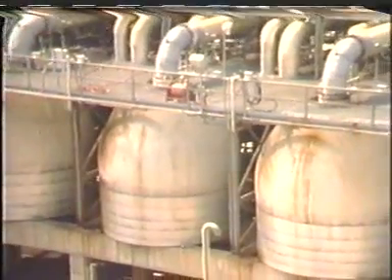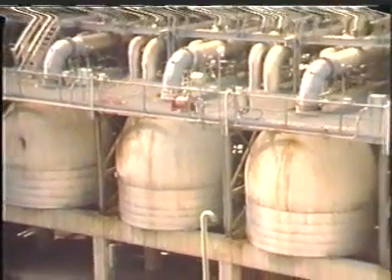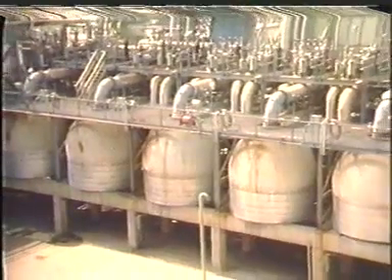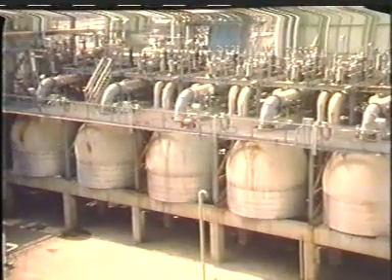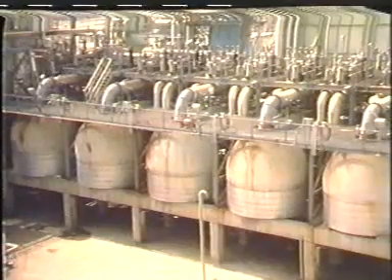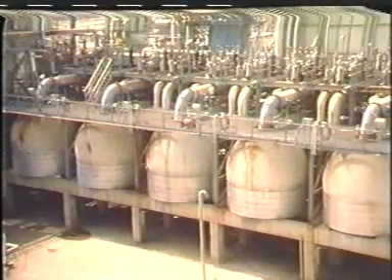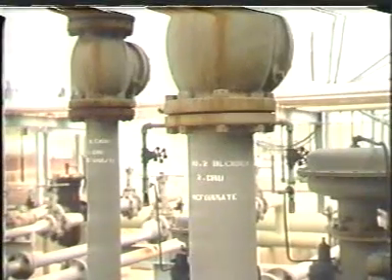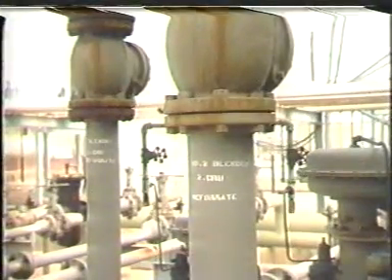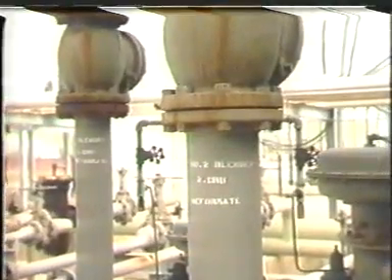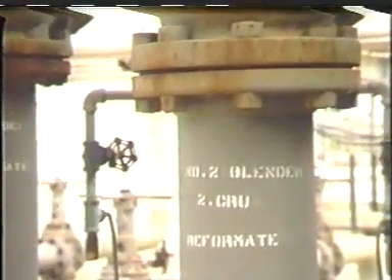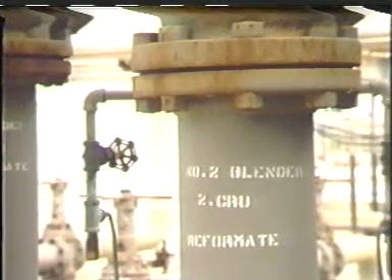Reforming occurs inside a series of reactors where the feed is contacted with the catalyst. The catalyst promotes several chemical reactions which reform paraffins and naphthenes into high-octane aromatic compounds. The product produced by catalytic reforming is called reformate. Reformate may be used as a petrochemical feedstock or as a gasoline blending component. Secondary reforming products include hydrogen, along with some light hydrocarbons.